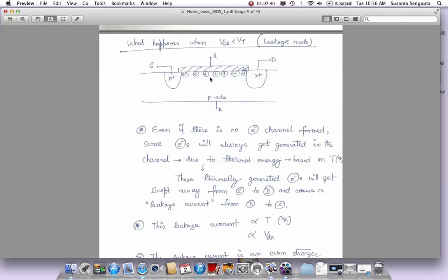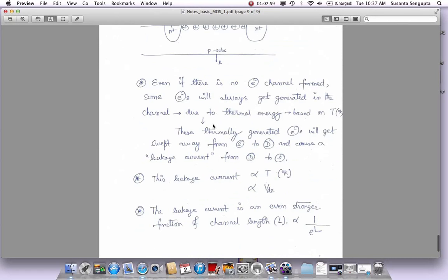It's not really helping with the thermal process, but the electrons want to go over this hump here. There's a reverse bias diode, and they want to go over that hump. This voltage could come in here and give them energy to jump across that hill. That's the hill these carriers see in the reverse bias diode, but they just jump across. So leakage increases with VDS.